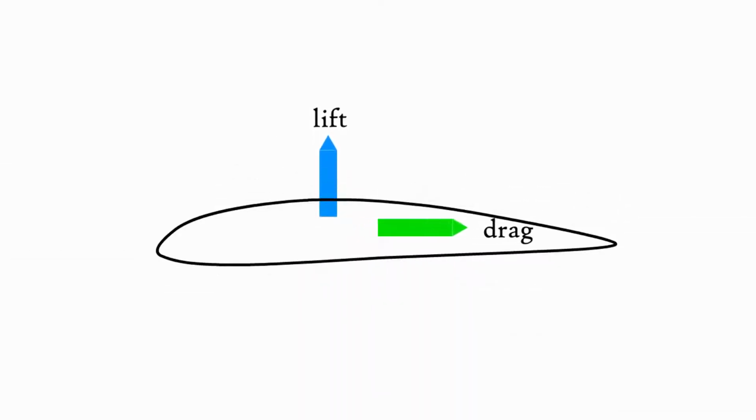With the pressure distribution over the top and bottom of the airfoil, we can determine the aerodynamic lift and drag forces on the airfoil. So with this method, we know we can calculate lift and drag on an airfoil if we know the velocity field. But this leaves us where we still need to determine the velocity field. Once we obtain the velocity field, we can use the Bernoulli equation to calculate the lift.